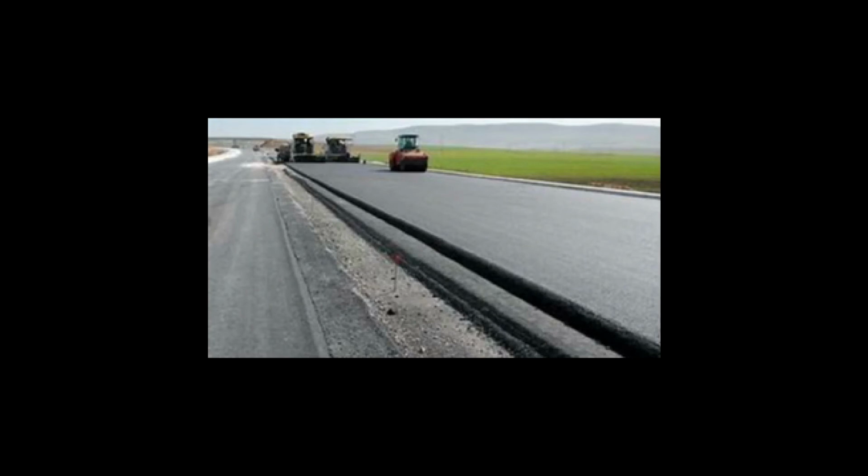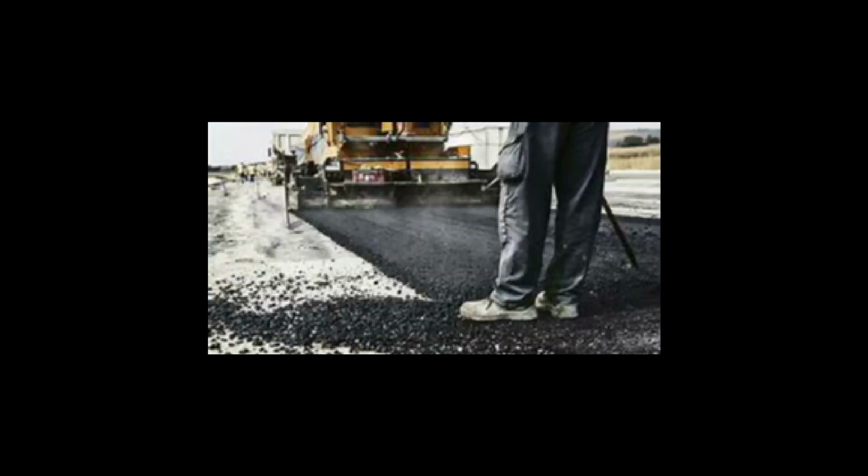Another kind of roadway surface is made with bituminous concrete. This is a kind of cemented aggregate using crushed stone as a coarse aggregate and sand as a fine aggregate. Asphalt is used as a cementing agent instead of Portland cement. Asphalt is a black tar substance which can be found in pools or lakes on certain parts of the Earth's surface. It also can be manufactured from petroleum or from coal.